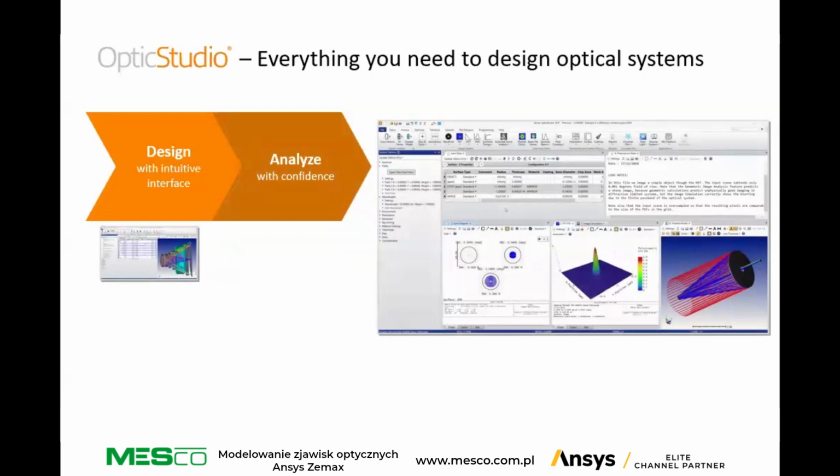The software includes the typical engineering tools to analyze the performance, such as aberrations, spot diagrams, wavefront error, and it also offers other more specific tools like full field aberration analysis to improve free-form designs, contrast analysis for MTF optimization, and image simulation to produce photorealistic images of your object scene.